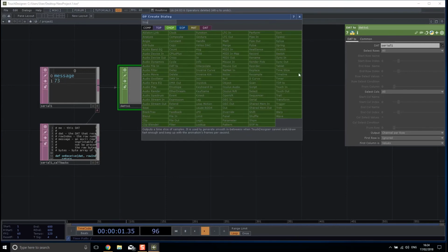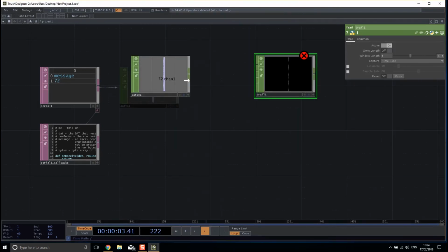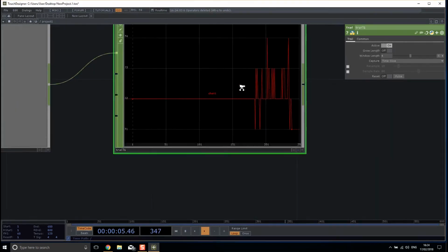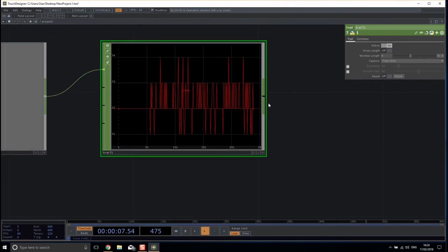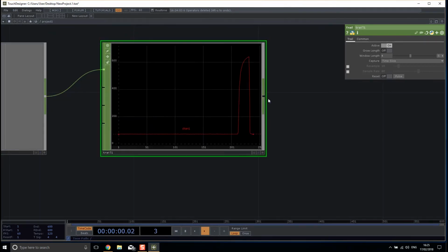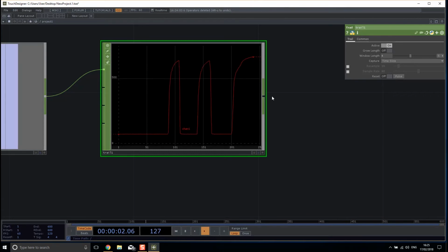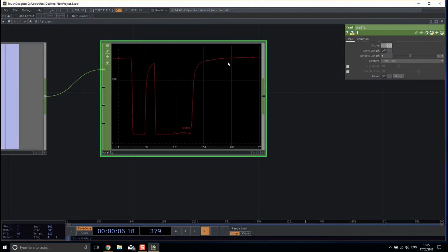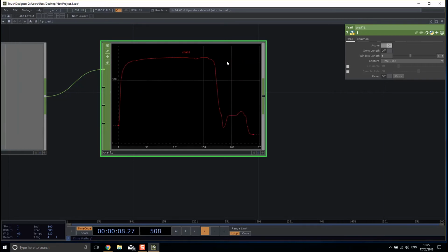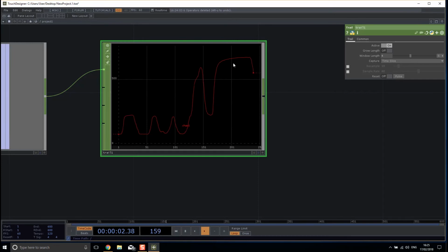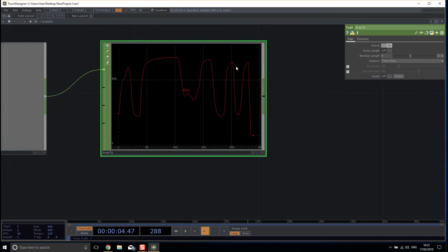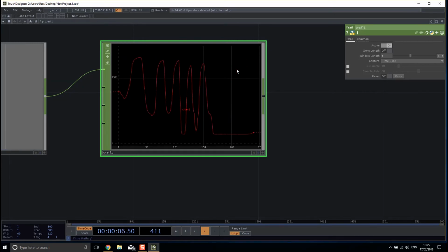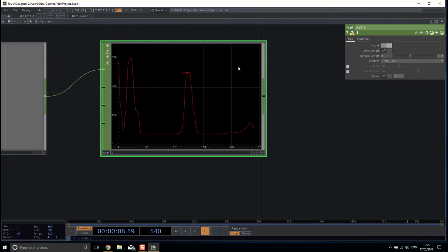I could visualize it nicely for you. So this trail shows us a running total over the past 4 seconds of what is happening. And you can see anytime I cross it, we get that beautiful arc up and down. And the reason it arcs like this is because some of the laser light is still touching the sensor until I completely occlude it. So it's not a straight on and off reading that we get. It's a partial reading based on how much laser light is actually getting past my finger.